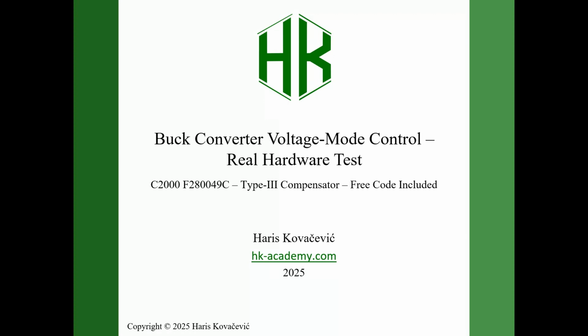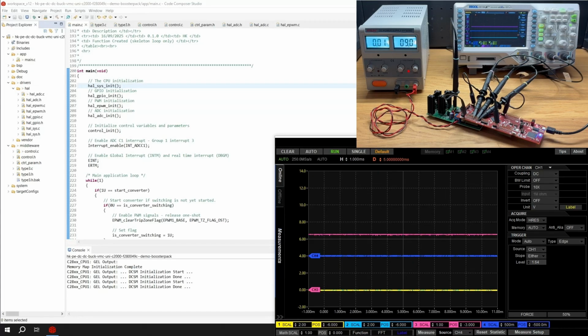The goal is not to show the full code implementation, that's part of my course, but rather to show you the practical behavior, the transient response, and how closely the real converter matches the LTspice model. On the screen, you can see two things. In the upper right corner, the complete hardware test bench: the F280049C LaunchPad, the TI buck converter board, the power supply, and the oscilloscope. In the bottom right corner, you will see the live oscilloscope window, where we will observe the output voltage, PWM signals, and load step waveform.